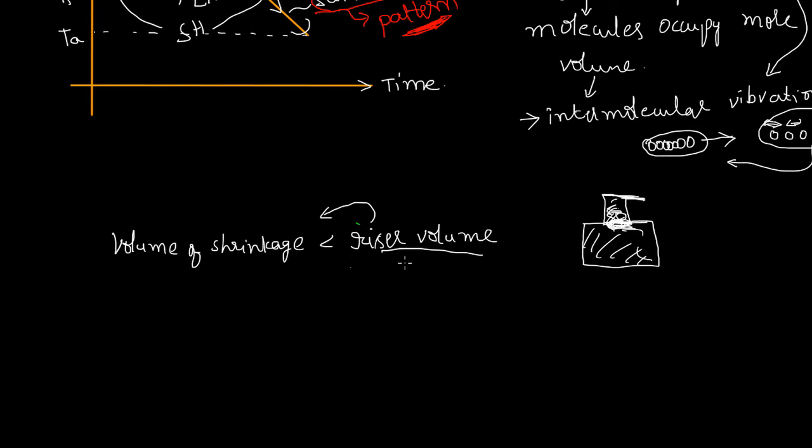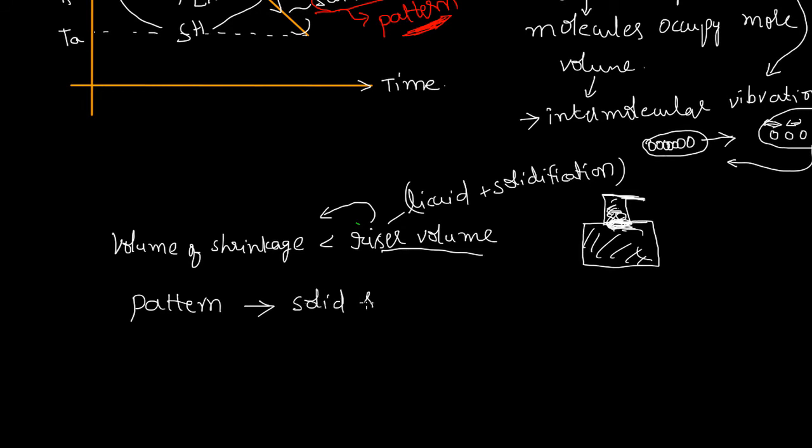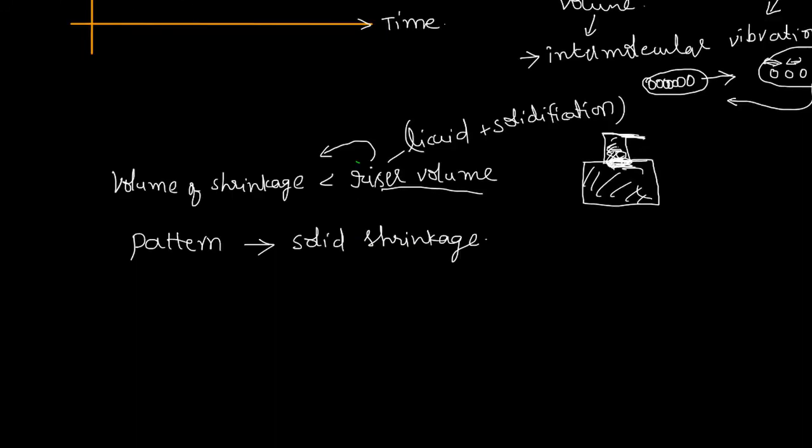So riser will compensate for liquid and solidification, both shrinkages. Pattern will take care of solid shrinkage. Different materials shrink differently, right? So some of the values I have collected, I will show you in 1 minute. Wait up to that.